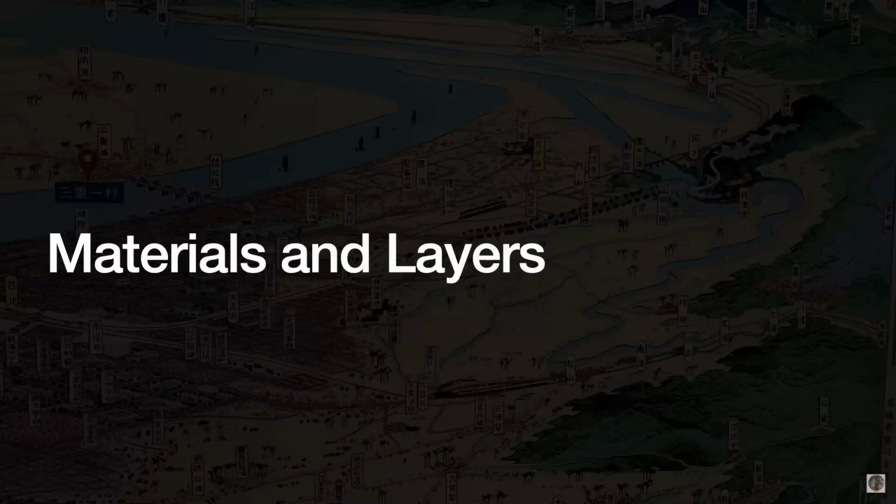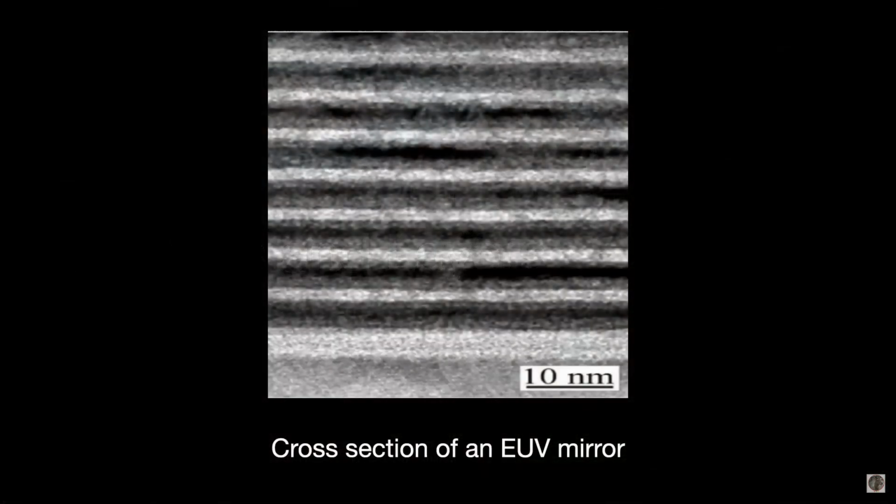The D-spacing, as in the width of the bilayer, has to be perfect. The molybdenum is about 3 nanometers thick and the silicon about 4 nanometers. The D-spacing being off by just a little bit hurts reflectivity by a huge amount. A 3% deviation in D-spacing leads to a 36% decrease in total reflectivity.